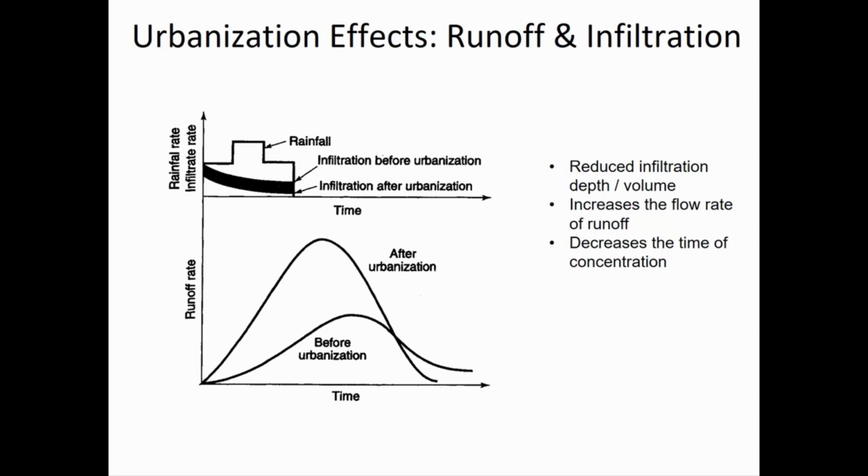When water is flowing over a grassy surface or forest litter, there's a much higher roughness value than water flowing over smooth pavement. So, number one, we changed how quickly the water is able to move over the surface, and especially when we add channels in. If you think about a gutter or a pipe, water is able to flow much more efficiently through an engineered conduit than it can through a natural channel.